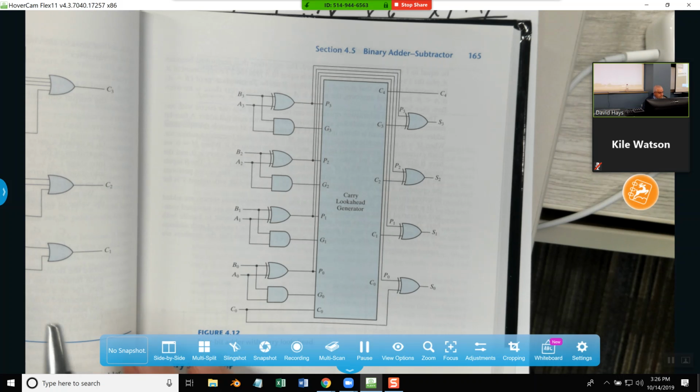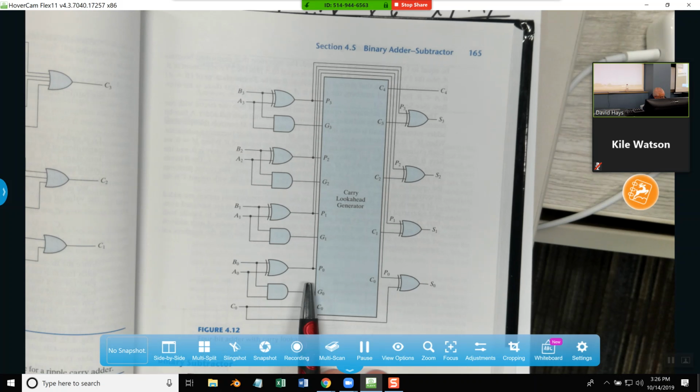Okay, full adder. Addition of n-bit binary numbers requires use of a full adder. And the process of addition proceeds on a bit-by-bit basis, right to left, beginning with the least significant bit. After the least significant bit, addition in each position not only adds the respective bits, but also does the carryover.